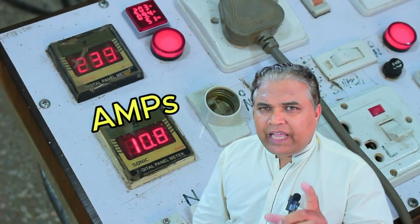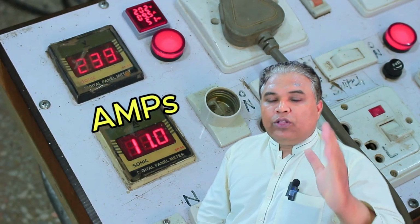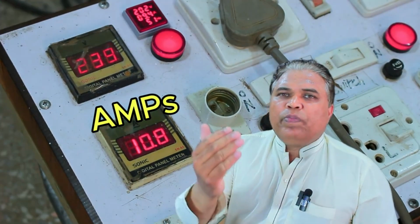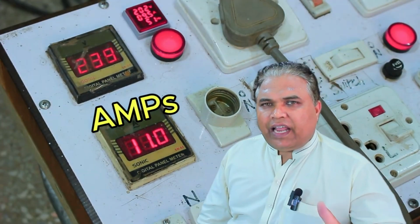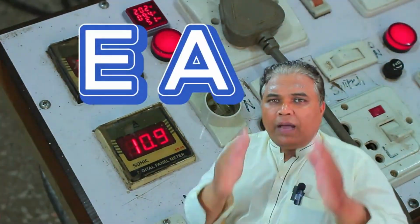As I mentioned earlier, you need to keep an eye on the current because it was getting too high. This was happening because the outdoor circuit board was not detecting the current properly. That's why it was pulling in more amperes to check the system. Sometimes the current flow was high, sometimes low, but when it wasn't analyzing the current properly, it showed the EA error on the indoor unit's display.